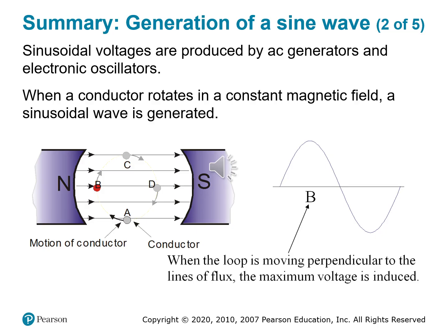And this is the physics behind our power grid, our car alternators, and portable generators. As the coil rotates past this point, the output voltage reaches its maximum, then begins to decrease again as that angle shifts. What we're watching is the sine wave take shape in real time. It's driven by rotation and the geometry of the field.